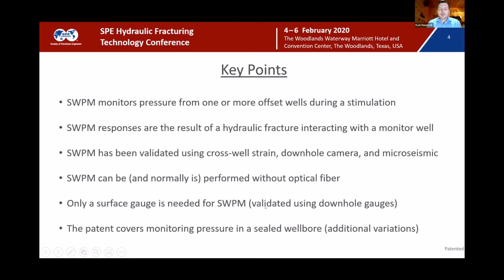You'll see SWPM throughout the presentation. That's the acronym for sealed wellbore pressure monitoring. A bunch of engineers came up with it, so the name's not very unique. It really is what the name says. We have a sealed wellbore, and we're using it to monitor pressure as we frack an offset well. The easiest analog I like to use is imagine putting a pressure gauge on top of a water bottle full of water and squeezing that water bottle.